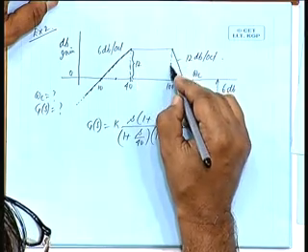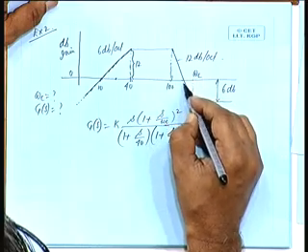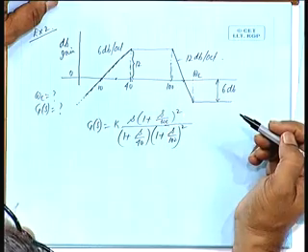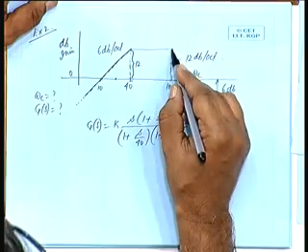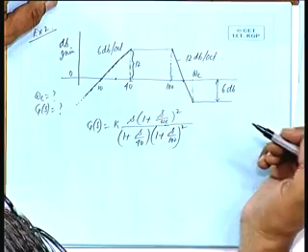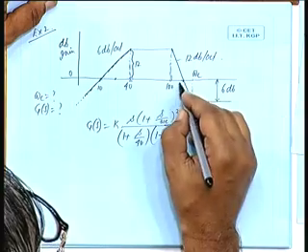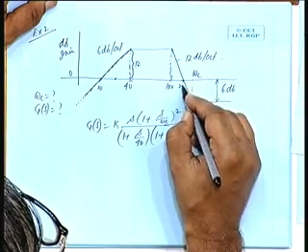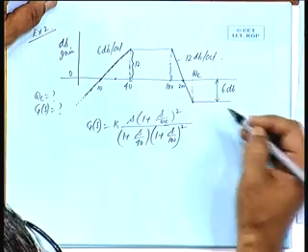Okay. So, from 12 dB per octave, if it is falling, so how much is this? It is falling at the rate of 12 dB per octave and it has fallen by 12 dB. So, how much is this? This frequency 200, 100 to 200, this is the octave, and 200 to omega c it is 6 dB.